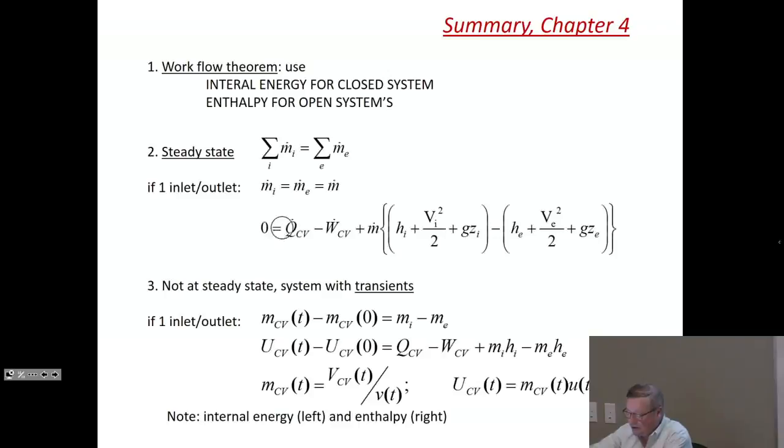And then your equation becomes this general equation that we have used quite a few times. So equilibrium in steady state comes from balancing the rate of heat exchange in the control volume, the rate of work in the control volume, and the mass flow rate multiplied by changes in enthalpy, changes in kinetic energy, and changes in potential energy.